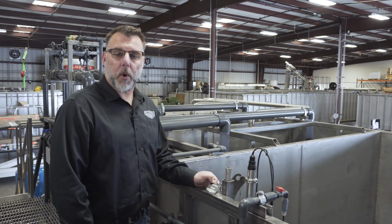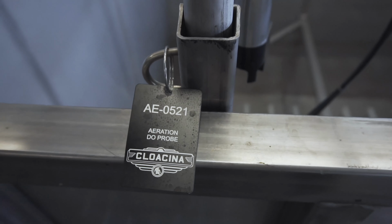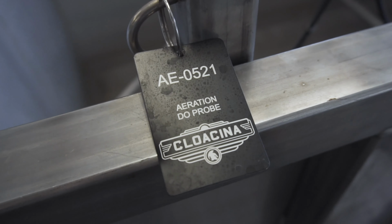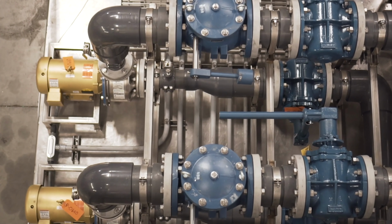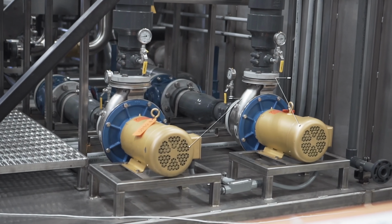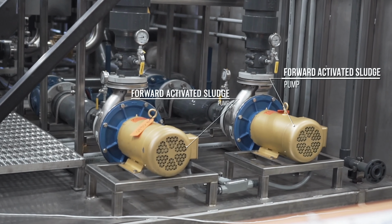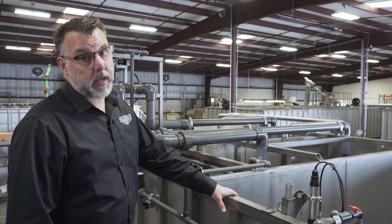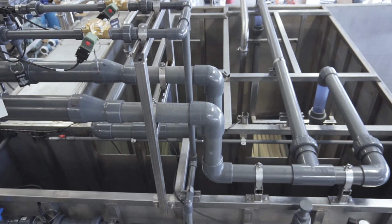You'll notice each component on this system is supplied with a laser etch tag. The tag numbers match the panel and the O&M manuals. This unit utilizes forward activated sludge pumps located on the integrated equipment skids. Activated sludge is pumped from the second chamber to our membrane process.